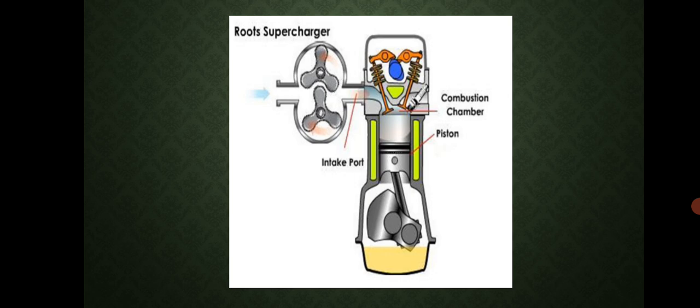However, in a petrol engine, when the density of the charge is increased while keeping the fuel of the same octane number, the compression ratio has to be decreased to avoid detonation. But with a decrease in compression ratio, the thermal efficiency also decreases, which is not preferred.